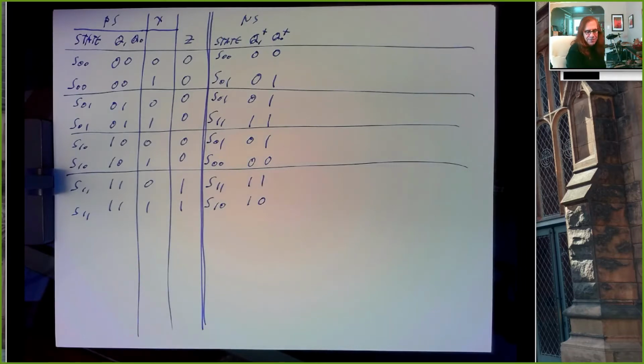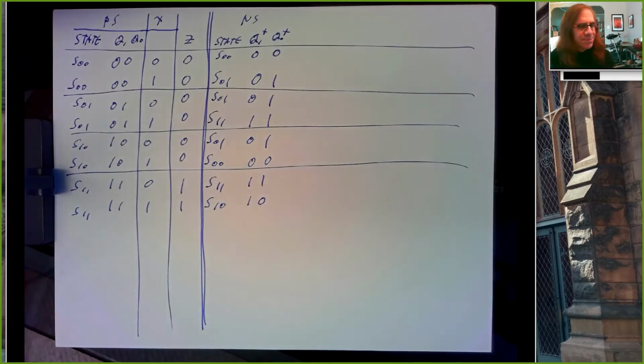What was the last question? The last one was changing the encoding to what we call one-hot encoding. But for 4 states and 1 input, you end up with 32 rows in your transition table, and that seemed too extreme. But we'll do a one-hot encoding example in class.